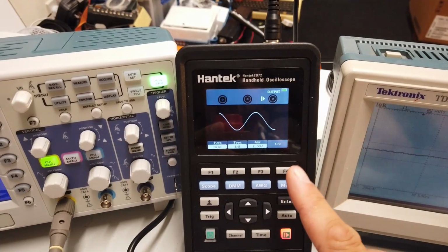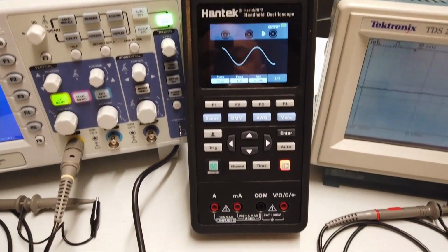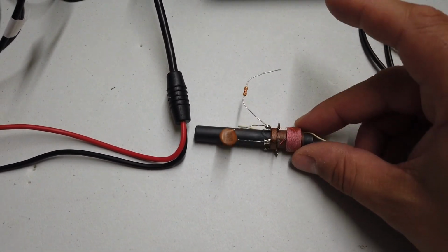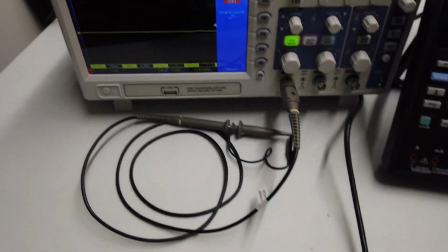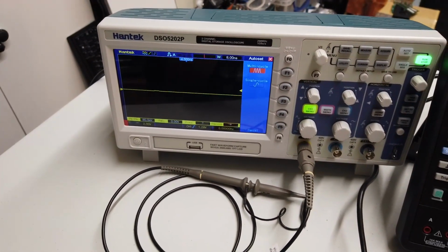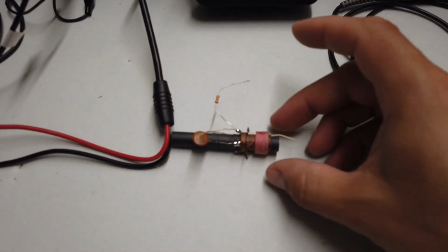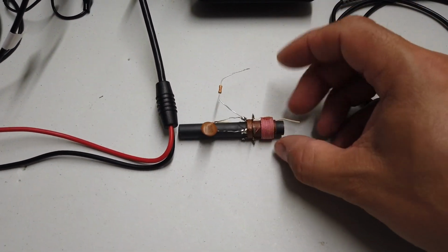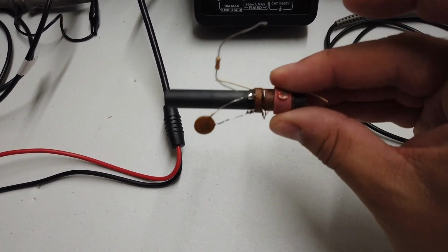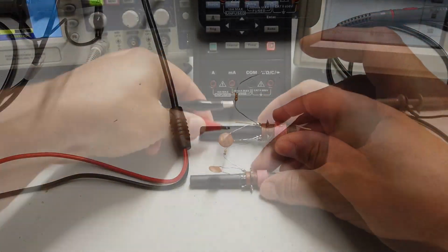So what we're going to do is set that wave generator up. We're going to sweep it through a variety of frequencies, connected across this little tuned tank circuit here, and we'll see what frequencies that tuned tank circuit responds to on the oscilloscope, and that will give us an idea of the tuning of this coil and capacitor. And this is the fundamentals of radio transmitters and radio receivers.